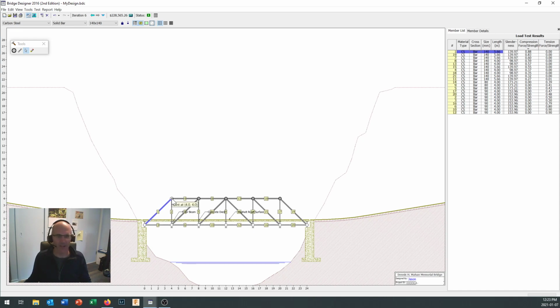And then this one would rotate downwards if it could, but it can't, because if it wanted to spin downwards right here, it would have to move in that direction. And all of these ones, the force coming up right through here is pushing right against there, keeping that from rotating downwards. So our end members right here tend to get the highest compressive loading. And that's what you see right on here. In fact, those two end members, number 19 and number 1, are loaded up to 88 or 83% of their overall loading.